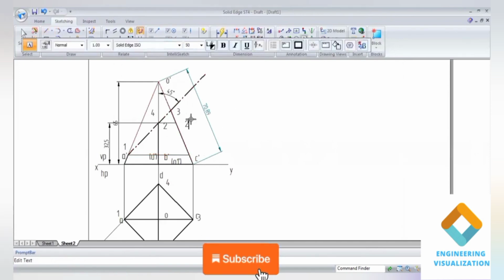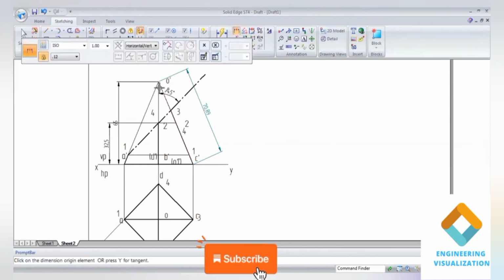You should do it. 2 and 4, and this is 1. 3, it is already there on the slant edge. And you need to measure this length because we need to cut the arc on the slant edge when we are drawing this development, right? We should know these dimensions. The slant edge lengths we need to find out.